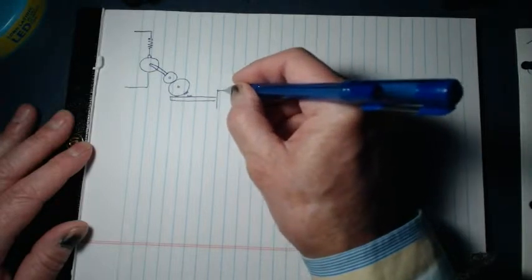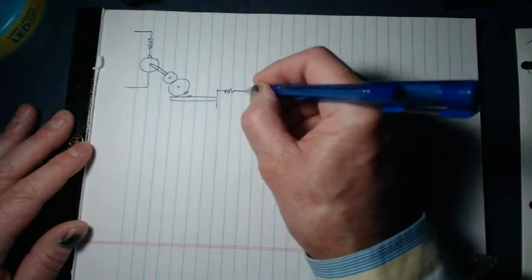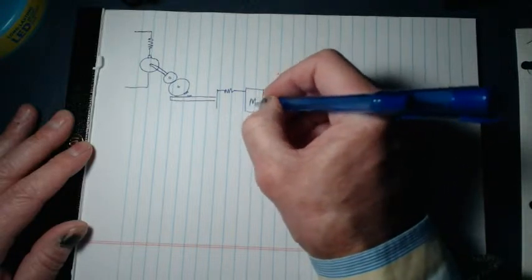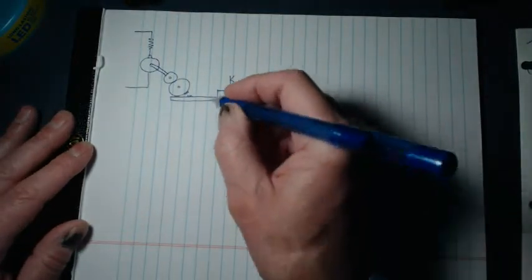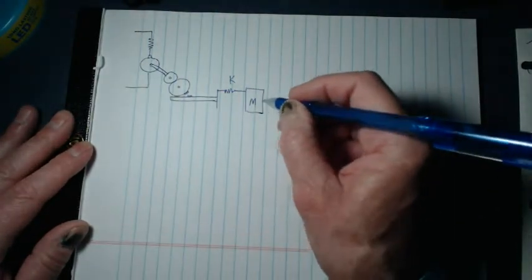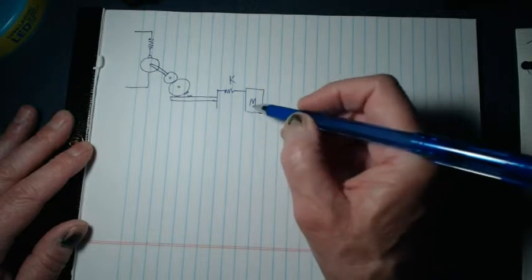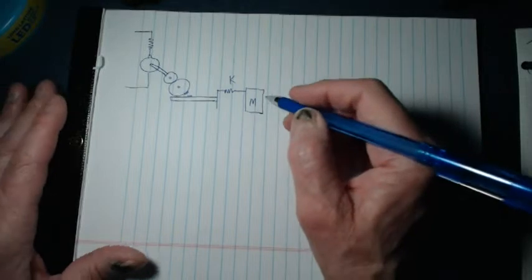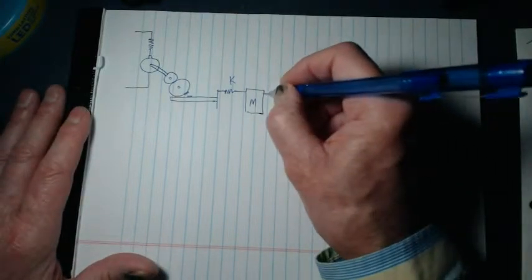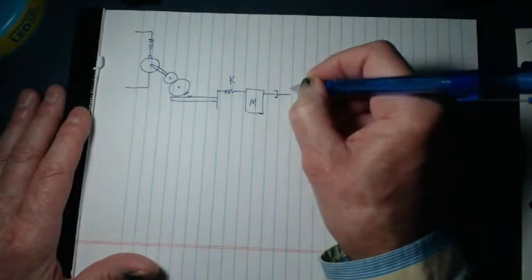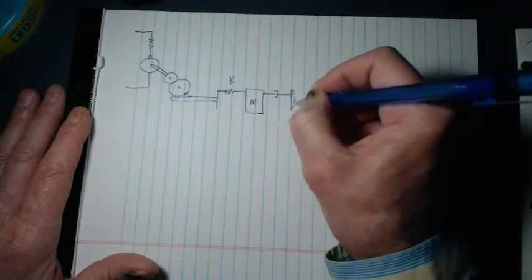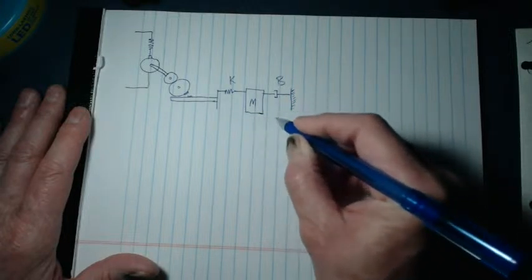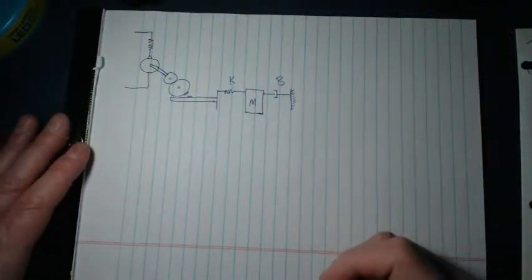I'm going to put this onto a spring that's pushing a mass. Sometimes I'll hook a damper between these two things, but that adds a slight amount of complication that I want to avoid at this point. So actually, I'm going to hook the damper to the outside wall. Another way of looking at that is that maybe this is sliding on a viscous surface. So we're going to have a damper that looks something like that.